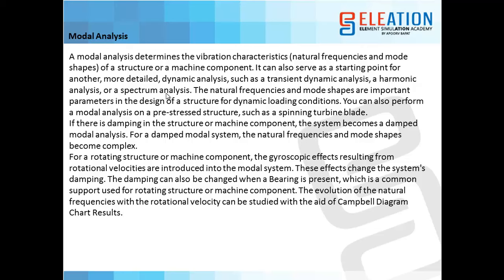The natural frequencies and mode shapes are important parameters in the design of a structure for dynamic loading conditions. This is because if there is a mode shape because of vibration, and the loading is applied on that particular mode shape or deformed shape, then that component is definitely going to fail. So first we have to find out the different mode shapes of that component and see that the loading should not come in the same direction where the deformation is taking place.